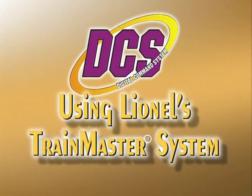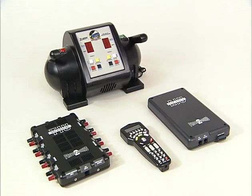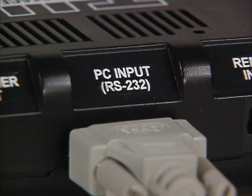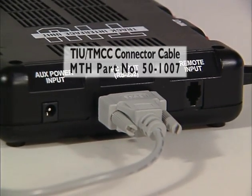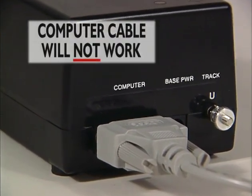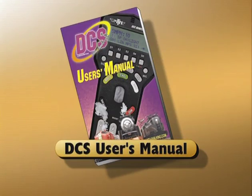The MTH DCS system can also control locomotives using the Lionel Trainmaster command system. In addition to the MTH DCS components we have already shown you, you will need the Lionel command base and a Trainmaster command-equipped locomotive. You will also need a special cable to connect the TIU to the command base. This cable is MTH part number 50-1007 and is available from your MTH dealer. Even though this looks like a standard computer cable, it is not the same, and a computer cable will not work in this application. See your DCS instruction manual for more information.